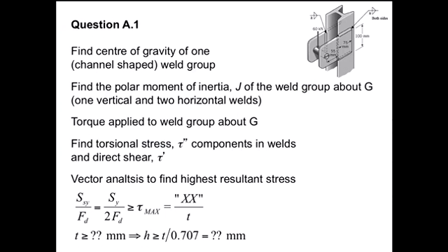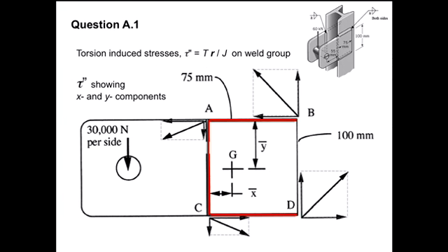So you've got to find your torsional stress and your direct shear stress, and apply an equation of some form or other to get down to throat thickness, leading on to the height of the weld, H. So it's just that standard triangle type form. Here's a schematic graphic of the overall process.